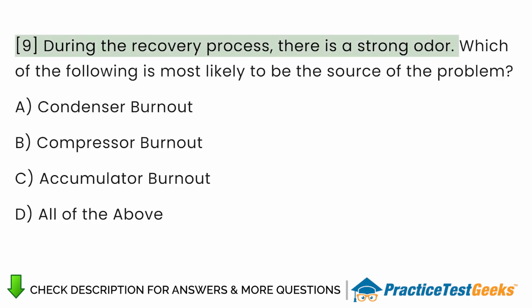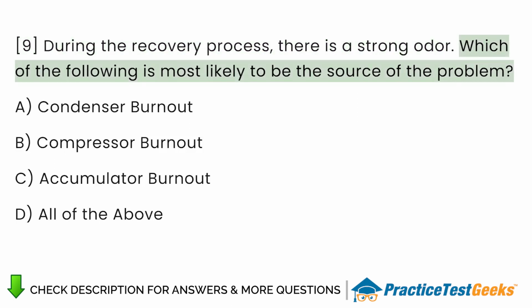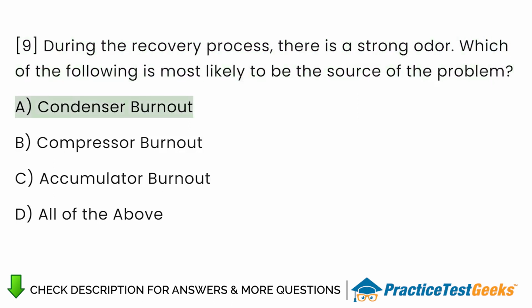During the recovery process, there is a strong odor. Which of the following is most likely to be the source of the problem? A. Condenser burnout. B. Compressor burnout. C. Accumulator burnout. D. All of the above.